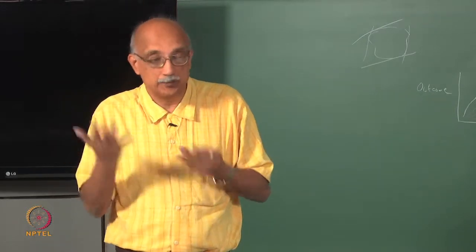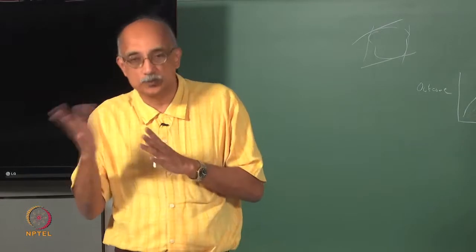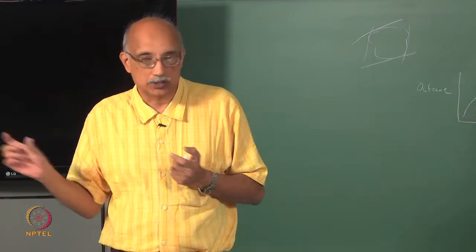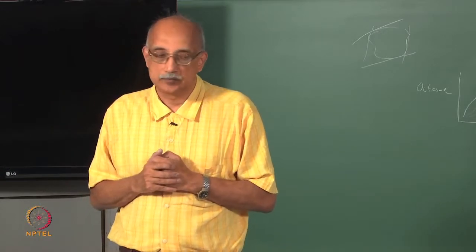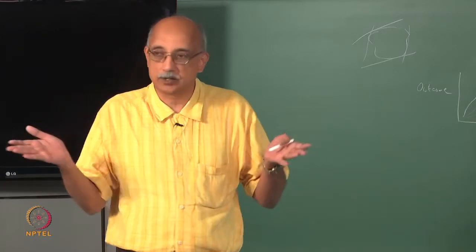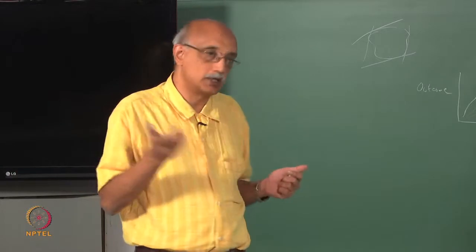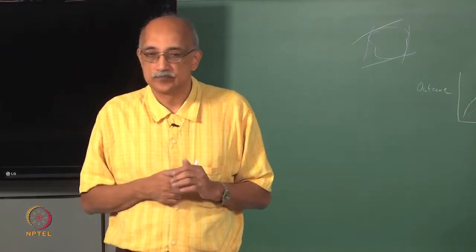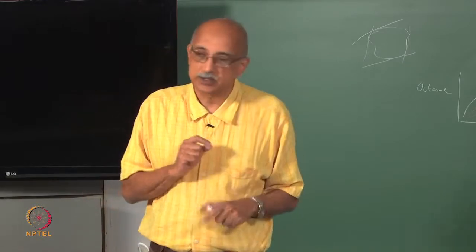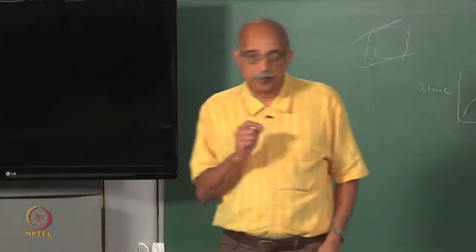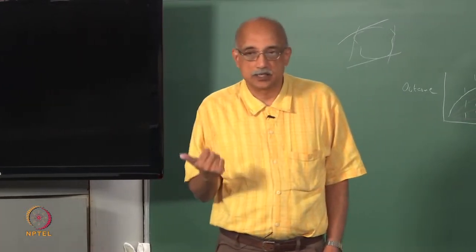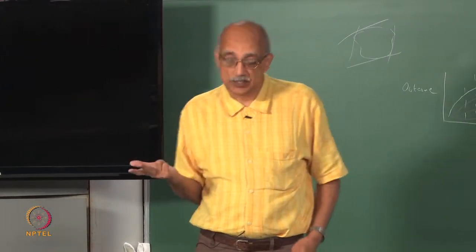As I mentioned earlier, breadth to length or length to breadth is a good measure of the elongation ratio. A perfectly elliptical particle would have a much larger elongation ratio compared to a spherical particle, for example. Sphericity itself is one of the key shape metrics. These are all called shape comparators, by the way: flatness, roundness, sphericity.